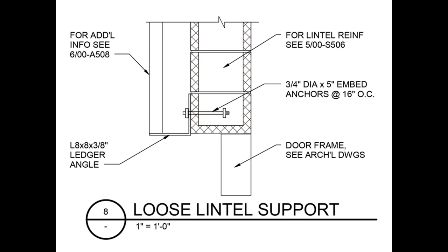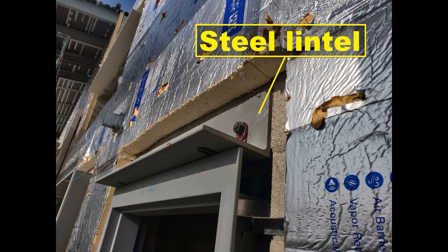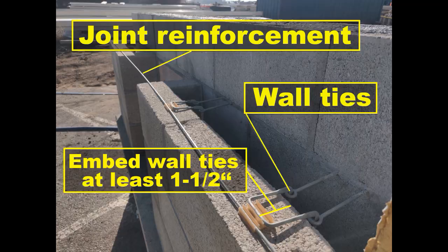Precast concrete and steel lintels. Provide precast concrete and steel lintels as shown on the drawings. Set lintels in a full bed of mortar with faces plumb and true. Provide steel and precast lintels with a minimum bearing length of 8 inches unless otherwise indicated. In partially grouted masonry, provide fully grouted units under the full lintel bearing length, unless otherwise indicated.